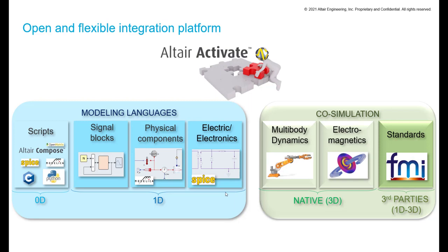You can co-simulate with any outside third-party tool that embraces the functional mock-up interface. So with any other third-party tool with which you could export a functional mock-up unit or a subsystem, you can bring that functional mock-up unit into Activate and co-simulate with that subsystem as well.